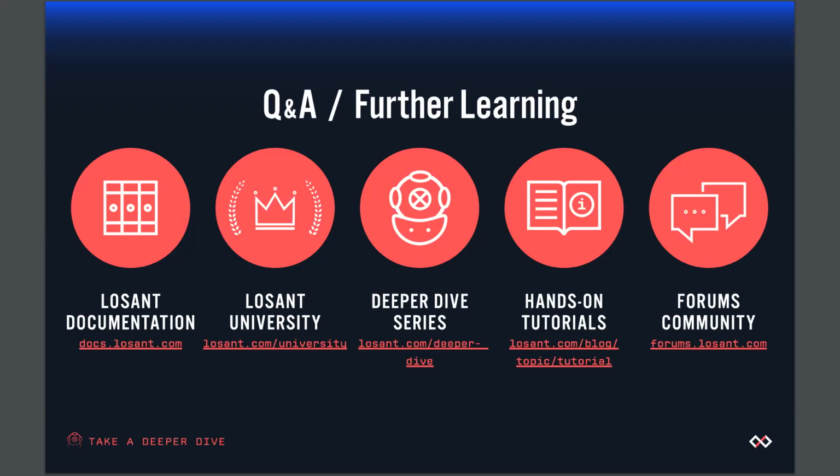The Rust instructions are then wrapped up in that API library that's also written in Rust. It's all optimized for the embedded environment, and it's selective on what code it puts in there. So it's as efficient as we could get it, and we're continually tweaking it as we go. Then from that Rust instruction, we compile it down to an optimized WASM bundle, which is then what is sent down to the device.